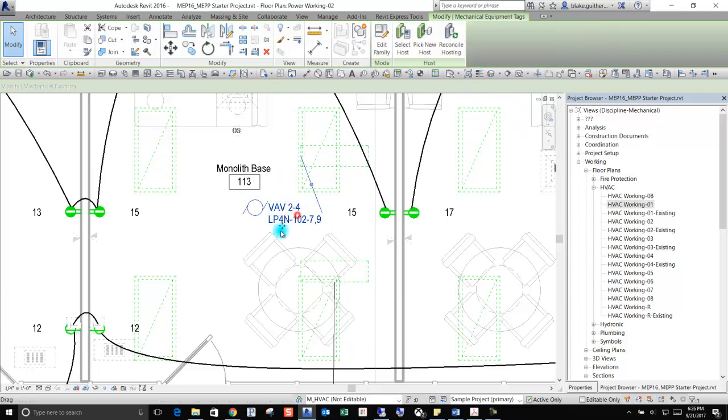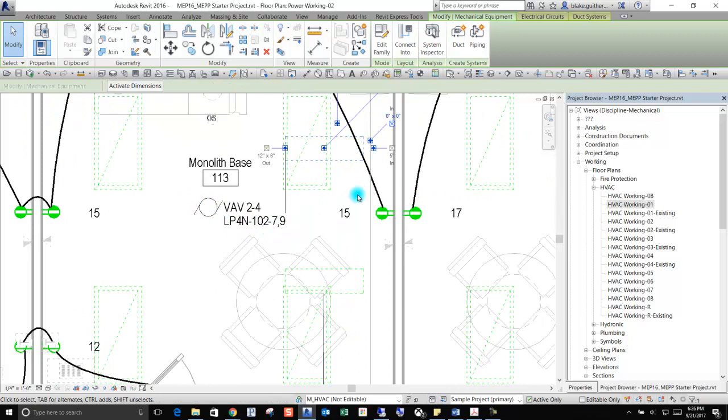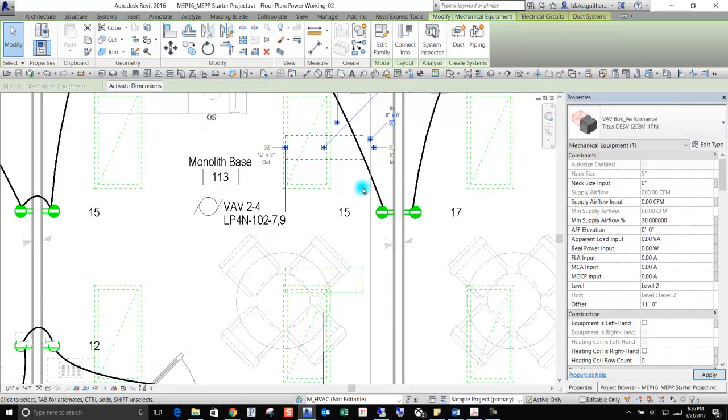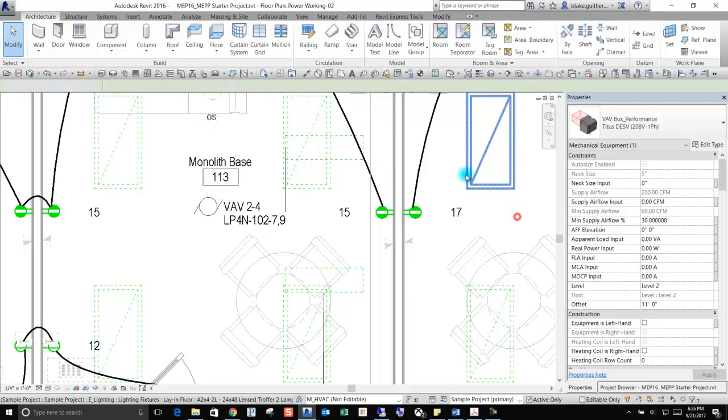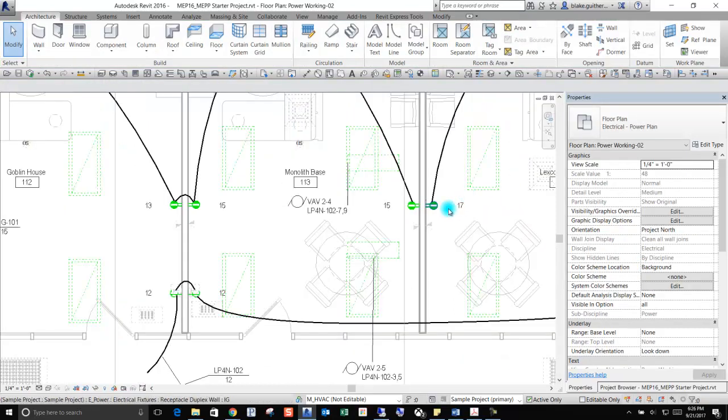So it turned green, with our filter. Now the tags are showing the information. So once again, the tags build upon that standardized set of shared parameters and how you can use them. And this electrical connector is now dynamic in certain senses. There's a list of overrides, which we'll talk about more in the user manual. But once again, we're able to get to the apparent load, which is at the connector, based upon a system of calculations. So it's important to have that parameter, apparent load, at the connector.